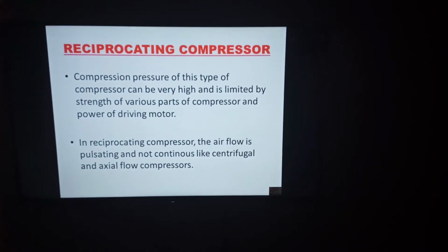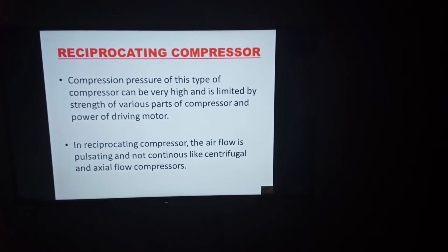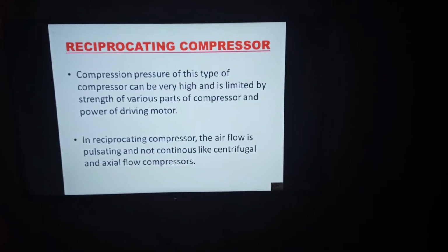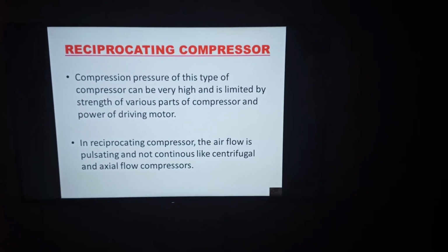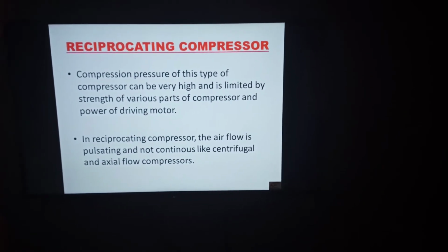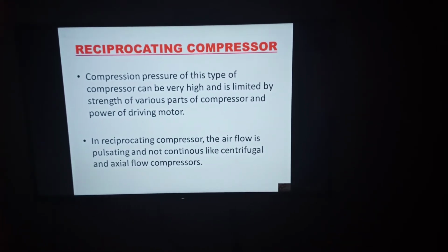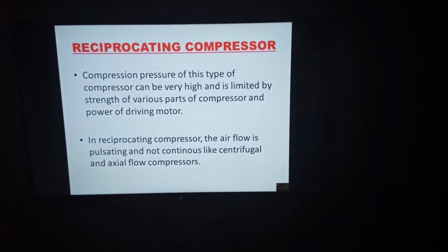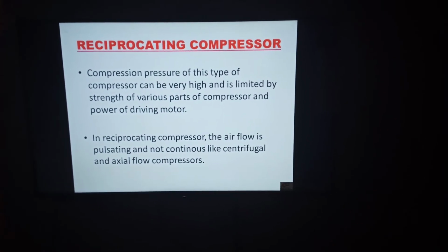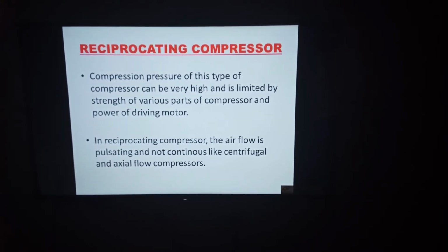So for applications which require medium pressure and continuous supply, we are using centrifugal and axial flow compressors. For applications which require high pressure, we are using a reciprocating air compressor. So this is the main difference between a reciprocating air compressor and a rotary compressor.